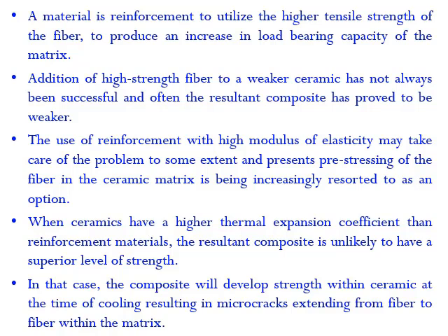In addition to high strength, weaker ceramics have not always been successful. Often the resultant composite has proved to be weaker. So when it comes to combining the matrix with the reinforcement, one has to choose wisely to form a composite material which leads to the proper desired properties. Otherwise the composite will develop stresses within the ceramic at the time of cooling, resulting in microcracks extending from fiber to fiber within the matrix material, meaning they are weak in tensile properties.